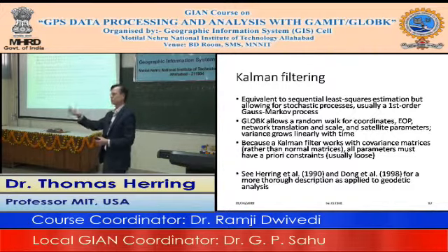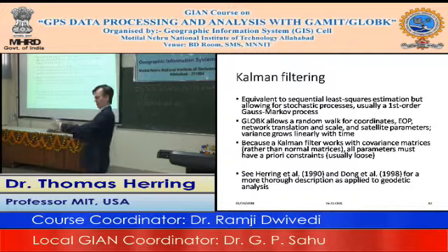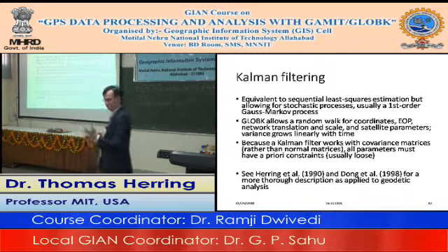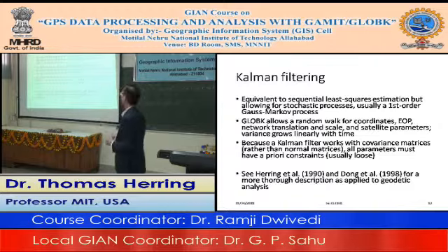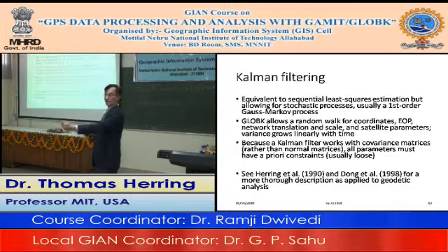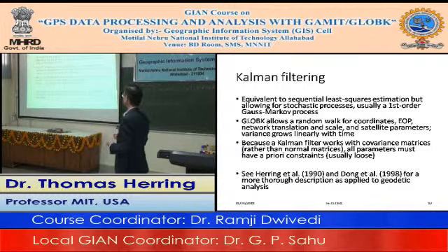The standard deviation grows as the square root of the distance you've traveled because you take constant length steps, 50 meters or 25 meters, whatever. Same process. So that's how you can calculate quickly for the number you get, how much is it going to be 1 year later? How much will this add on my uncertainty?